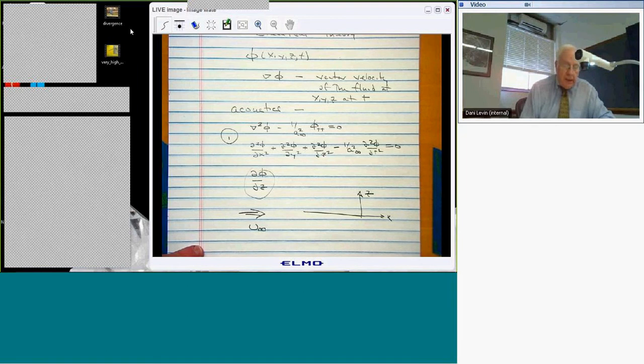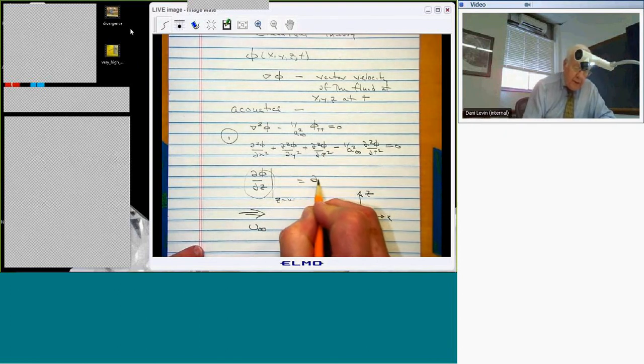Okay. And so if that body is moving up and down with a displacement w, then this velocity, which is the velocity of the fluid evaluated on the surface, that's z equals w. w describes the deflection of this surface. It must be equal to dw/dt. That's the velocity of the surface, right?